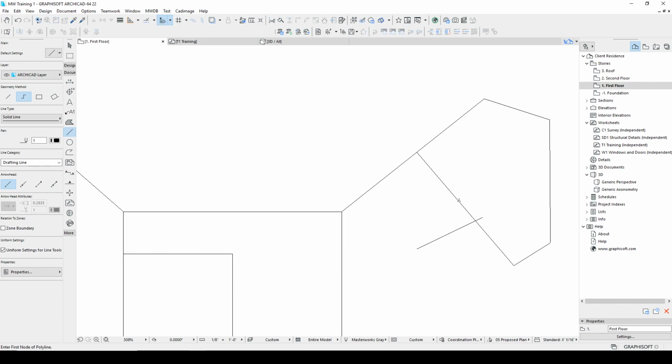If I delete this line, now here's a keyboard shortcut that I have to emphasize, and that's holding Shift to turn this into the selection tool. Even though I'm still in the line command, it's giving me the selection tool momentarily, so I can click and delete. Do not go up here and select this arrow tool. If you're doing that, you're wasting time and money.